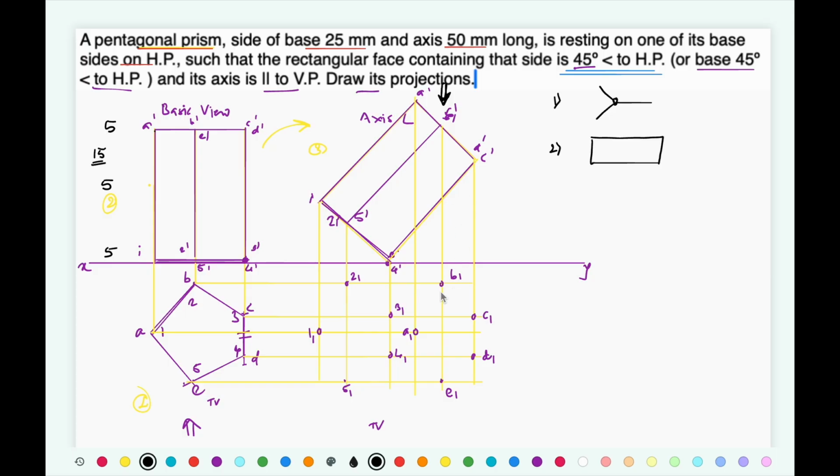So let's say ABCD is completely visible, so I will connect that pentagon first with all the visible lines. Now in case of that 1 2 3 4 5 pentagon, the outermost lines are going to be visible. According to rule number 2, I need to connect 2 with this B because 2B is one of the edges of the solid.